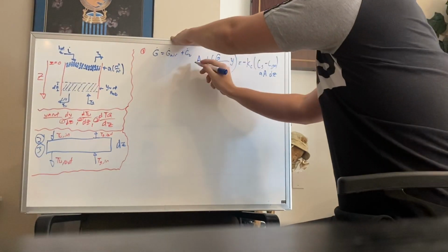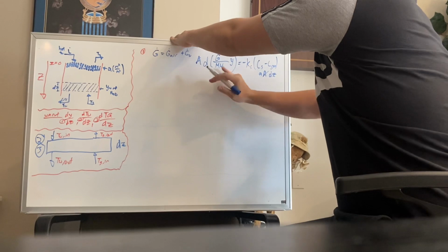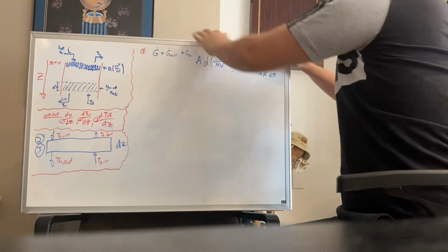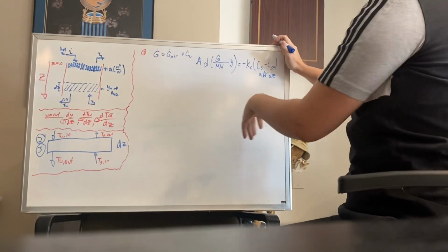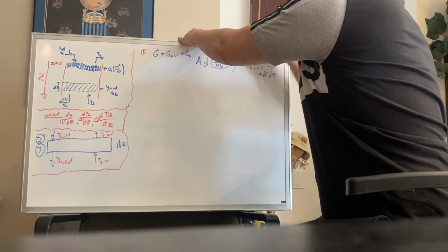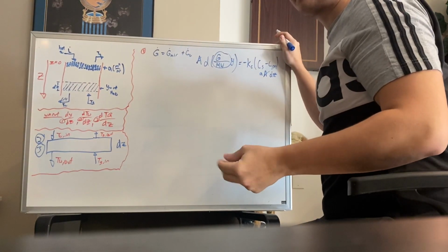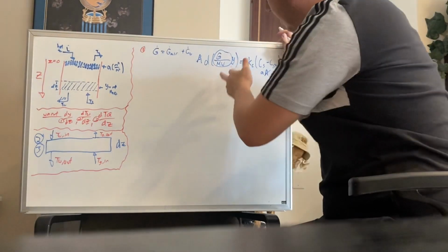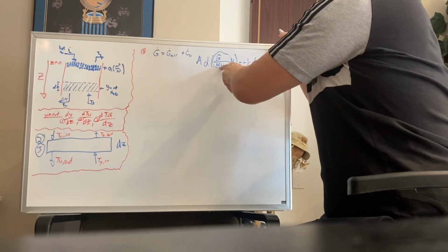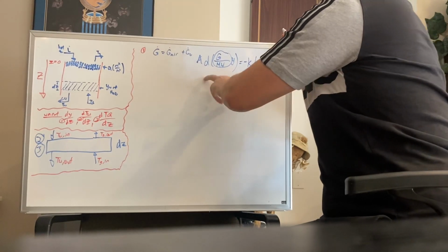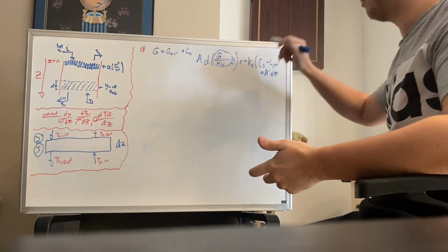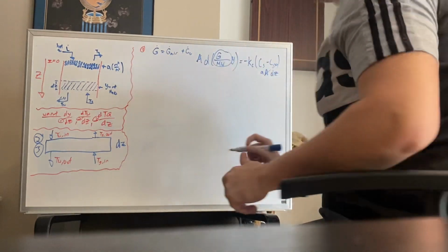We can see that these A's cancel out right away, and so that'll leave us with the differential change of the mass, the airflow rate over the molecular weight multiplied by the mole fraction, multiplied by what we have left over here. But we can actually take out this component right here, because it's going to be roughly a constant value. And so this will be nice because we can take this out and divide this over on this side, and that will end up leaving us with dy over here. We could just simply divide dz back over on that side, and that'll give us our dy dz value, what we wanted to look for, the rate of change of the mole fraction with respect to the change in area.